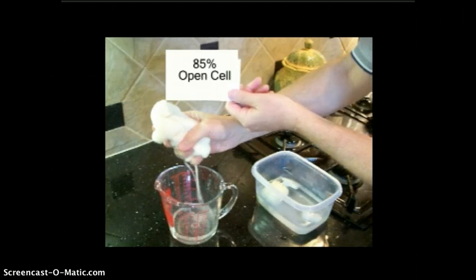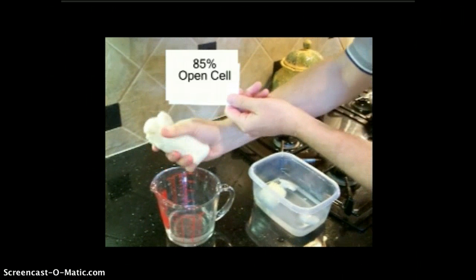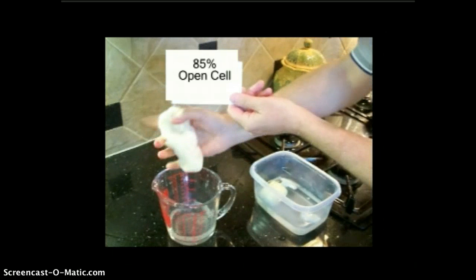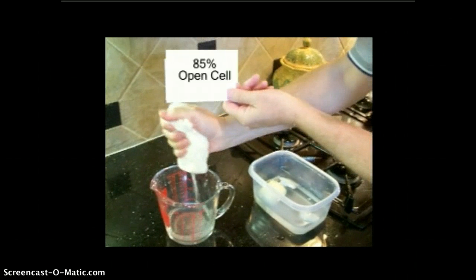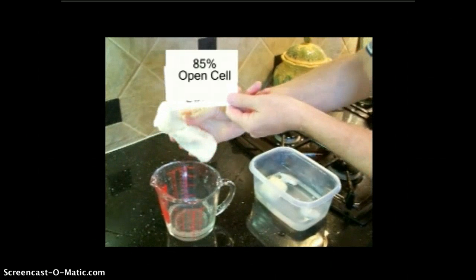The experiment shown here demonstrates that many products intended for wall and roof assemblies could absorb much larger amounts of water in contrast to the data sheet, which indicates that it is a non-absorbing product. If there is water leakage through the water-resistive barrier, the use of this material in wall cavities could create massive mold problems, since the normal wet-dry cycling will not likely occur.